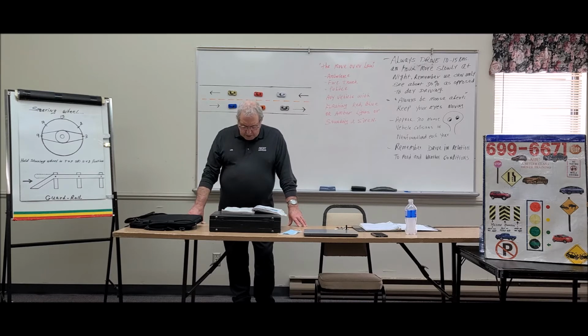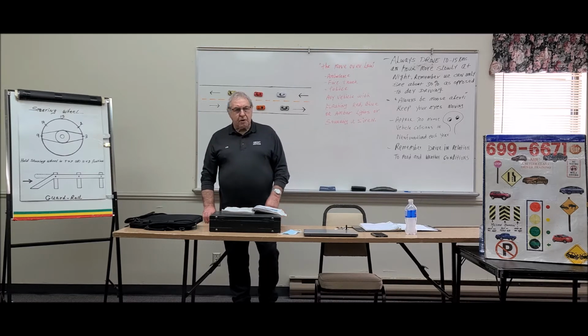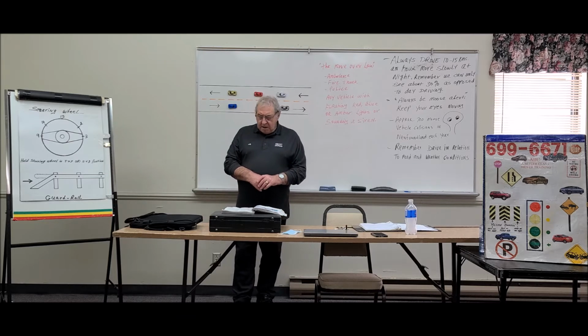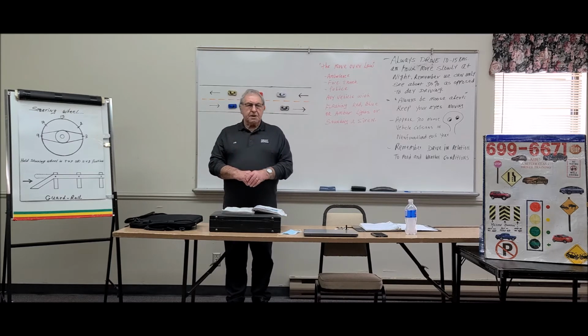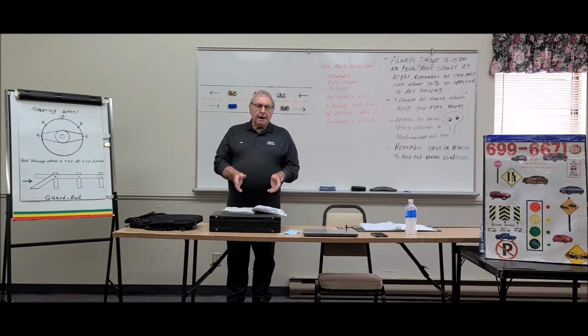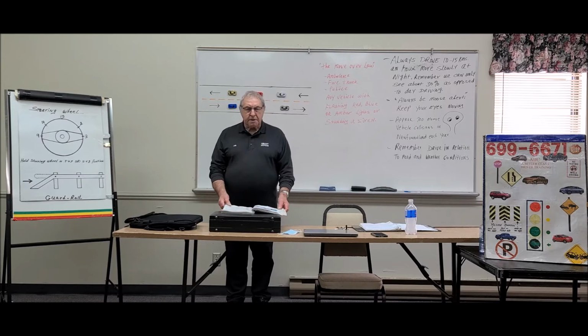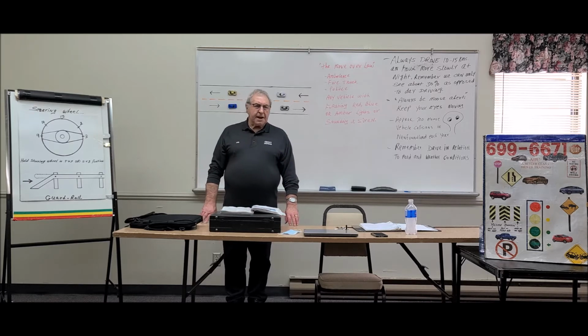The service engine soon light is not an immediate problem, class. The real answer to that would be to get it serviced and checked in the near future. So if you're driving down the roadway somewhere and your service engine soon light glows in your instrument panel, it doesn't mean you have to pull off the road and call a tow truck. You know, do your errand, and when you come home, make an appointment with your dealer and have it checked, just in case.